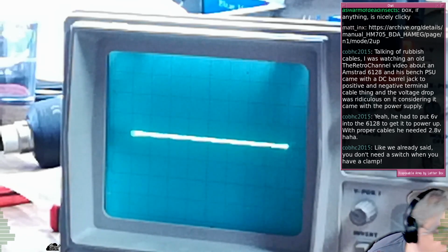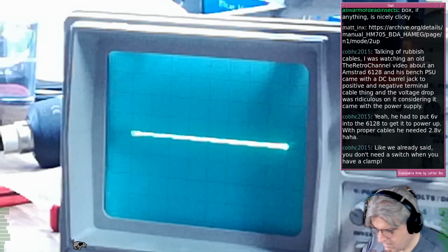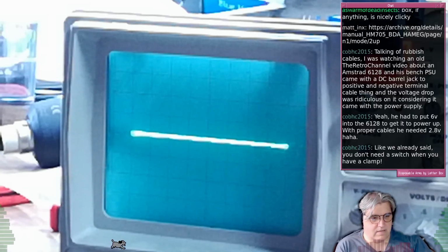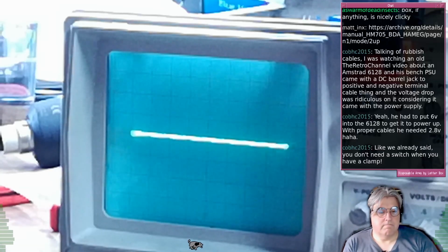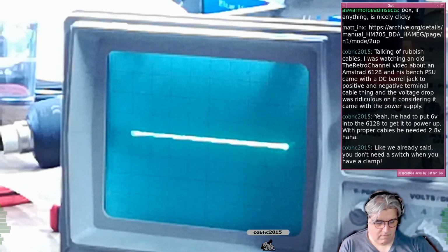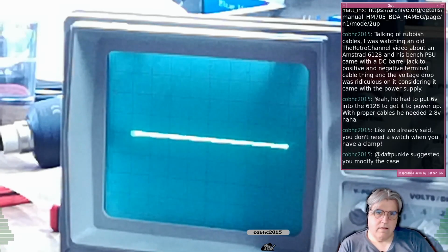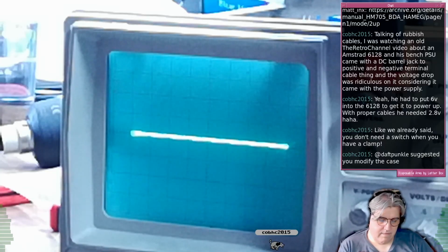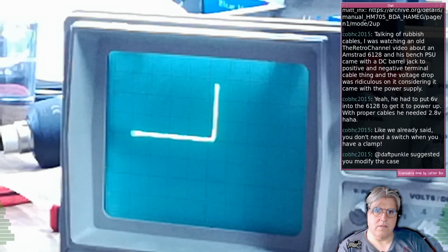Where's my new transistors gone? I've lost my transistors now. Oh, there they are. Right, this is one of the transistors that I've just bought in. Let us test one. This is middle pin to outer pin. And that gives us that one. So that is a BC junction apparently.